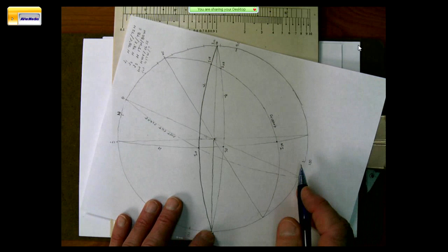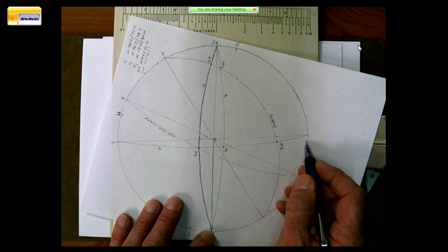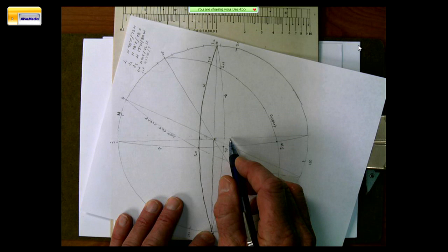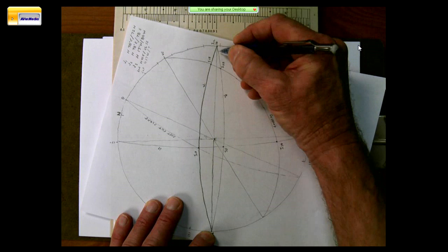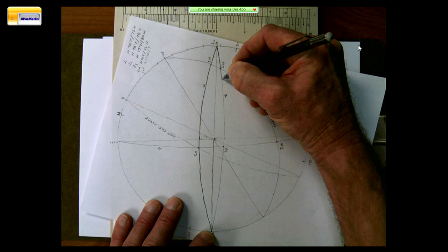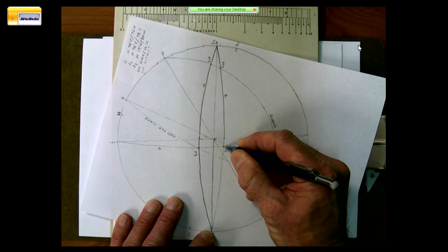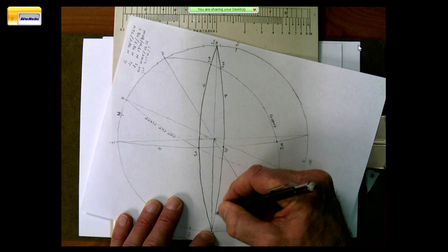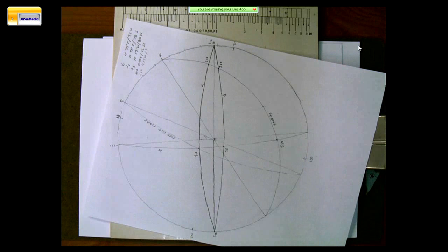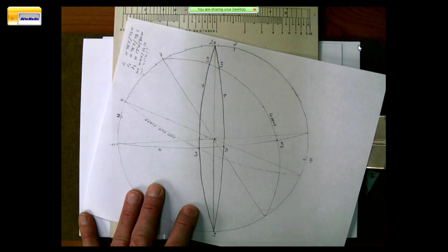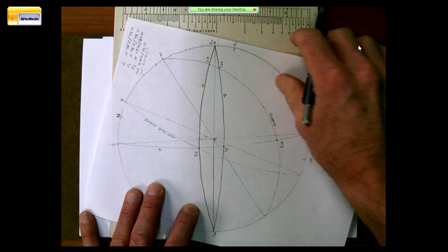So now I'm going to come in from the east side, and I'm going to count 10, 20, 30, 40, 50, 60, 70, 2, 4, 6, 7, 8. And I'm going to put another one going the other direction. Now these are simply planar representations of a series. This is an average value for a series, a joint set. It's an average for a joint set. And in the real world, we're going to have 10, 12 degrees variance, 0 to 10, 12 degrees variance with the strike and the dip.